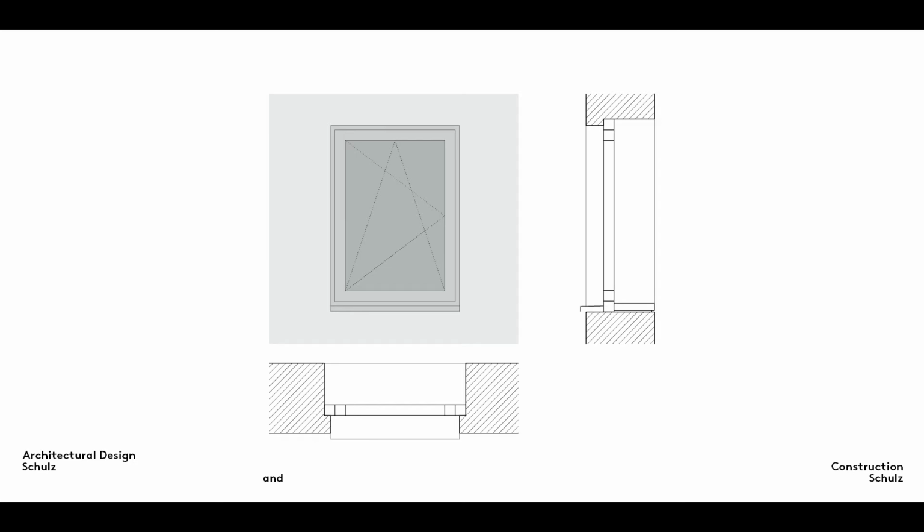The plan view of the window is placed below the elevation such that the vertical projection lines of the component edges coincide with the corresponding elevation lines. The same applies to the section which is arranged next to the window.